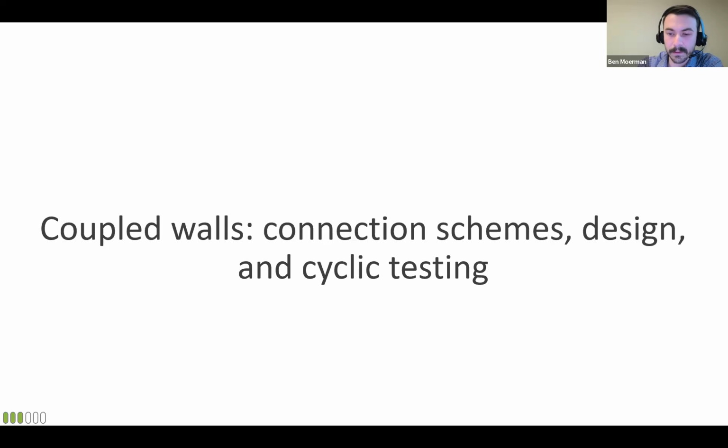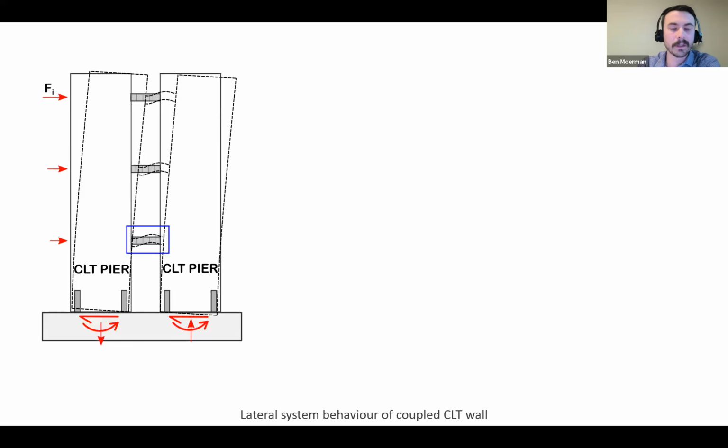So we'll first focus on the connections, and then we'll zoom out and look at the overall system test. Before we go to the connection, I just want to describe how the system's working. I'm sure there's probably several people on this call that have either designed or learned about designing reinforced concrete coupled walls. And really the system principles are exactly the same here. We have 2 walls that are paired together with link beams or coupling beams.